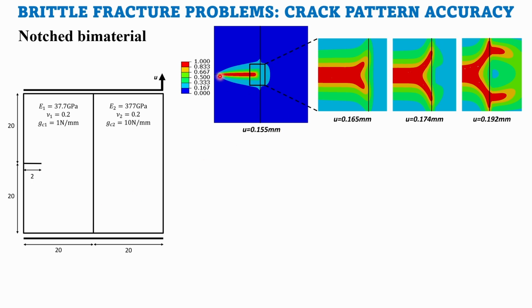Okay. So the crack will propagate straight through the weaker material, and when it hits the interface of the stronger material, we saw a crack split. So this crack branches into two, goes up along the interface till some distance, and it again enters the stronger material. And if you propagate this even further, these two branches will meet and they will travel along the center, as you expect in a mode 1 crack. But in the middle, near the interface, you will see crack branching and crack meeting.